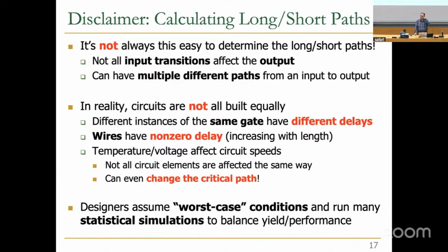Any other question? Yes. Why does aging of the circuit affect delay? Oh, aging. Okay. So aging can affect the effectiveness of your transistors, essentially. That's one reason, for example. Normally, you consider that your transistor, when it's on, can drive that much current.